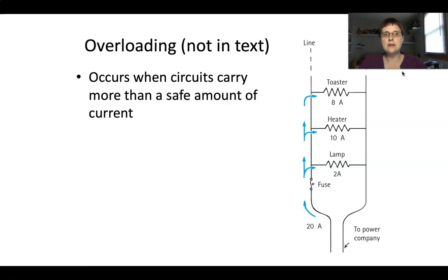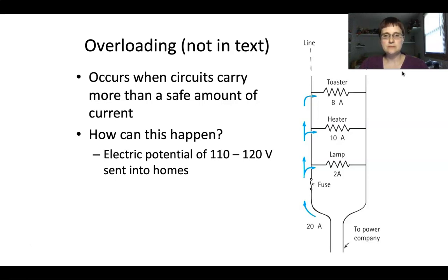So parallel circuits, these guys can overload because as you add more and more loads onto a parallel circuit, it increases the current in the circuit. So you may have been told to not plug too many things into a circuit. This is why. So let's take a look at how this can happen.